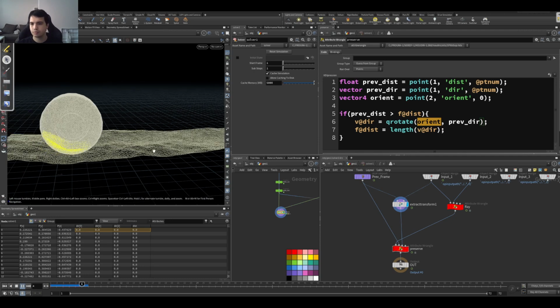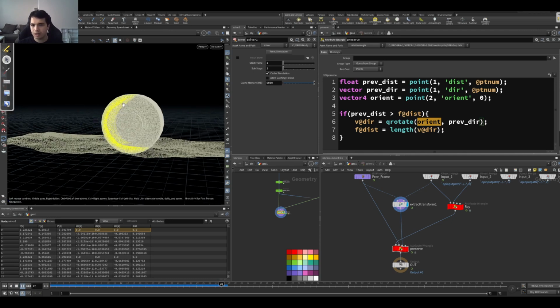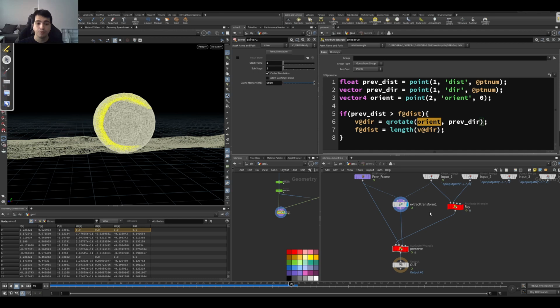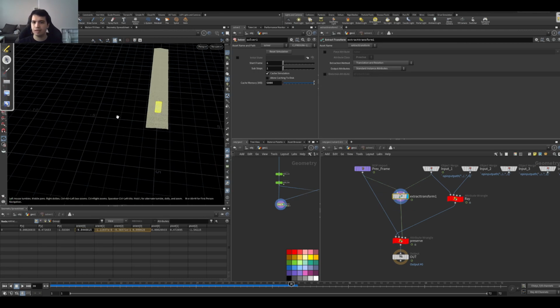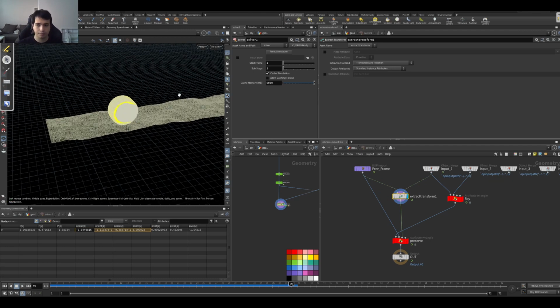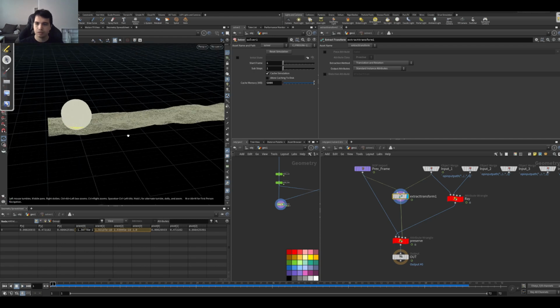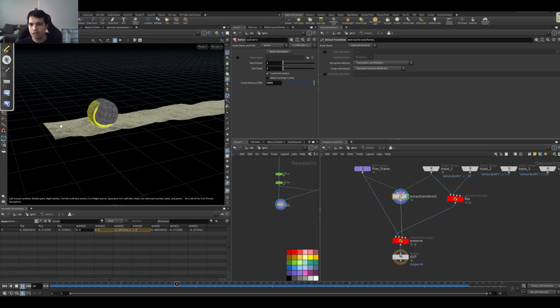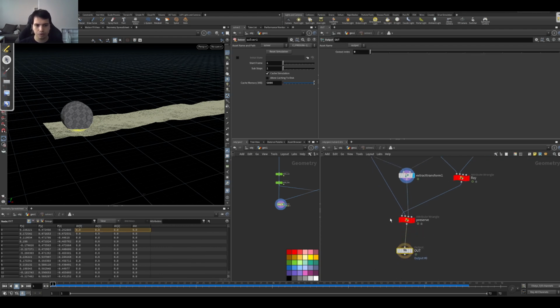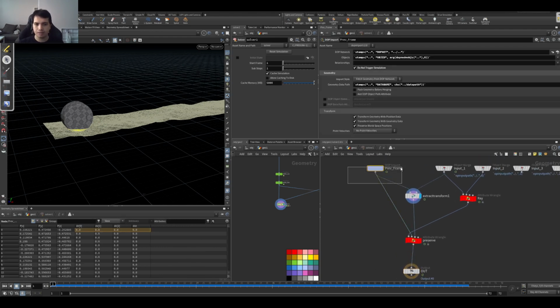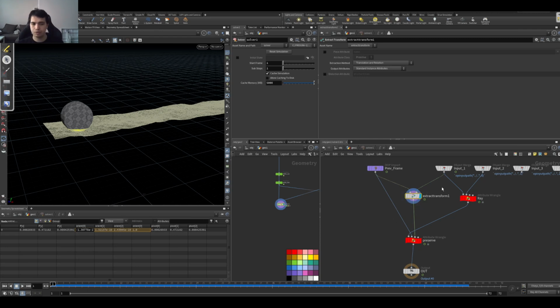Let's see. You see, they are looking inside, they are rotating with me. With doing this, you don't have to get stuck on a single axis. You can make a rotated tire in this manner. It will still work. I want to check out my deformations, but if I do it here again in the SOP solver, as my previous frame data will be changing in its positions, my extract transform might get messed up. So I don't want to do it here.